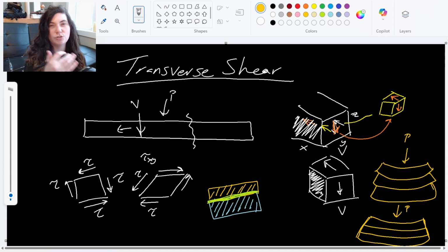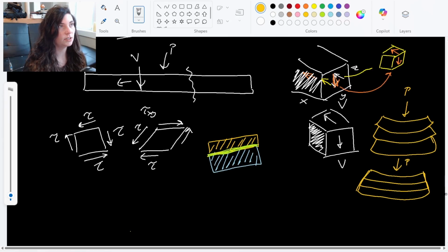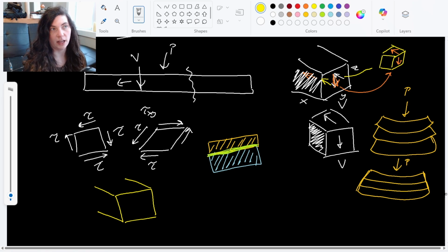So now there's stress at the glue between each of those beams. And even if it's not a composite, there's still stress within the beam itself. Within that beam itself, let's say we have just a square-ended beam like this. The shear stress is not one constant value.